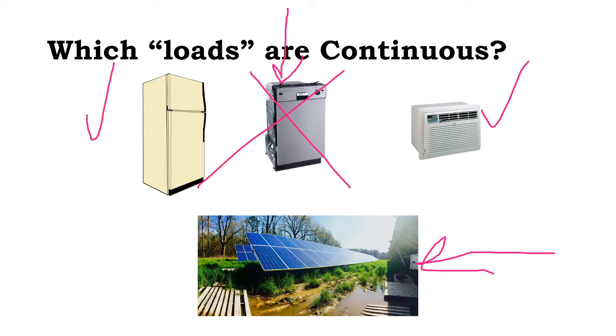It's not really a load because it's generating electricity versus consuming electricity. But if we were to treat solar as a load, and the general rule of thumb is if you have a switch, the larger power source, the grid side, goes into the grid side of the switch, and the solar array goes into the load side of the switch. Even though they're both power resources.